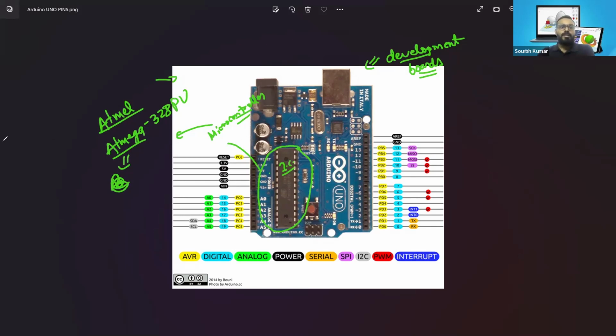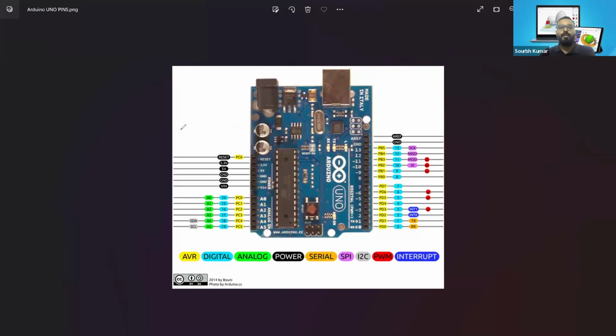Instead of the Arduino development board, we have several different types of microcontrollers present in the market, and some of them come at a very nominal cost, like the Node MCU. Node MCU works with the ESP8266 microcontroller. The Node MCU board is famous because it has Wi-Fi connectivity built in. But the Arduino board does not have any connectivity options built in. You have to integrate a Bluetooth module, or other Wi-Fi or GSM based module, to provide internet or connectivity. Since the Node MCU itself comes with Wi-Fi, we usually call those boards IoT enabled boards.